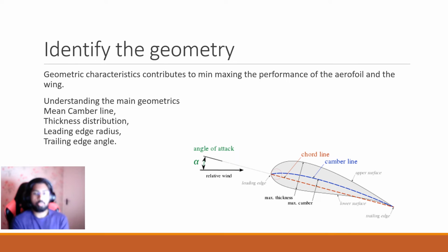At this point, it was important for me to determine the ideal lift coefficient for my aerofoil as well as the aspect ratio. However, the aspect ratio that I calculated here was only an estimate due to having an estimated wingspan.